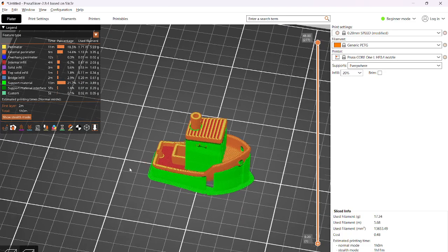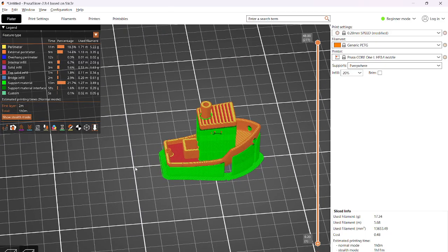So depending on the material, your print, sometimes your support material will outweigh the part that you're making, right? So it's something to keep in mind if you're going to be printing hundreds of the same part. If you can minimize the need for supports, you can make your parts cheaper. So that's kind of nice. Also, no post-processing, so same thing.